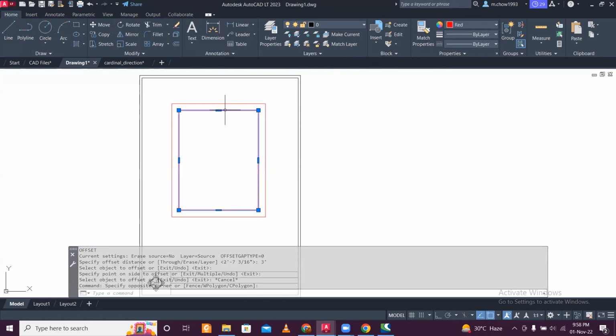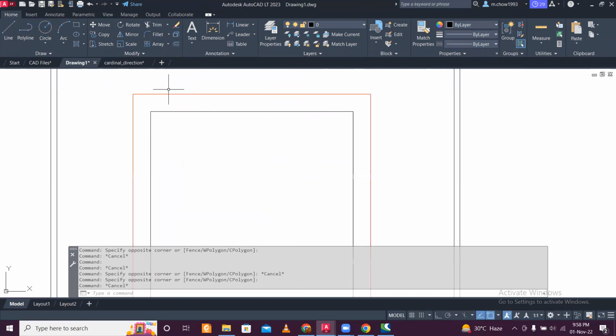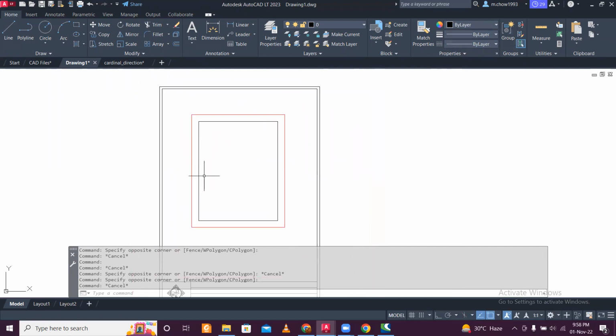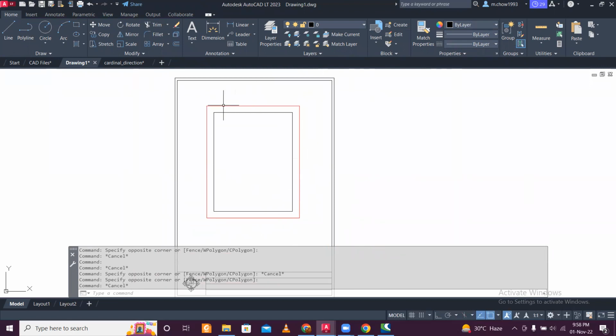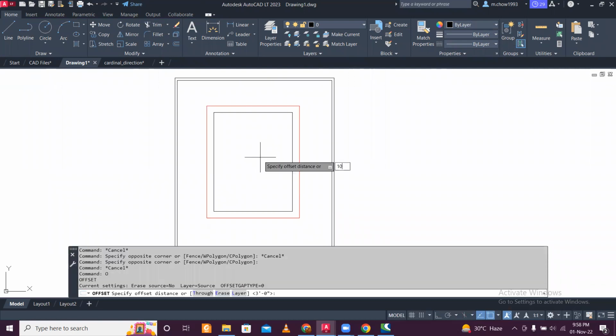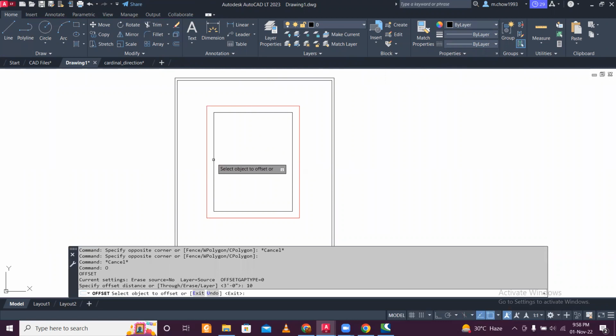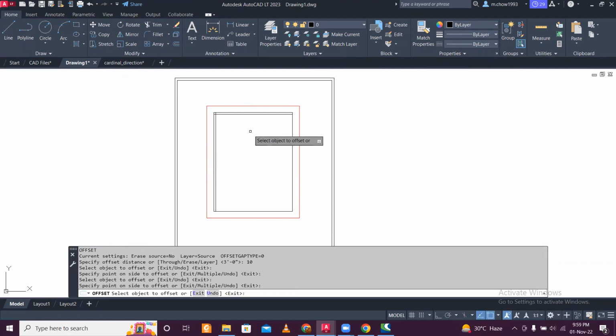And this one, let's select this and EX and select it. So it is exploded into 4 different lines. This one, we just change the color to ByLayer. So this is our building. We have left 3 feet on all the sides from the boundary, and in this particular area we will be constructing the building. So let's take outer walls of 10 inches. You can take the outer walls as 9 inches or 5 inches also, because in RCC it doesn't really matter much.